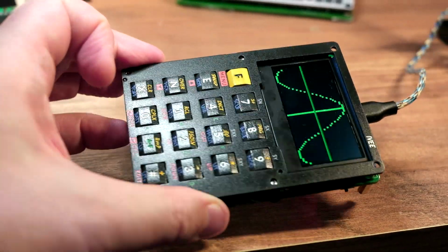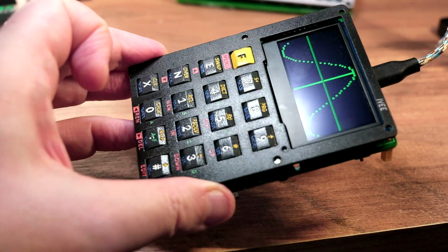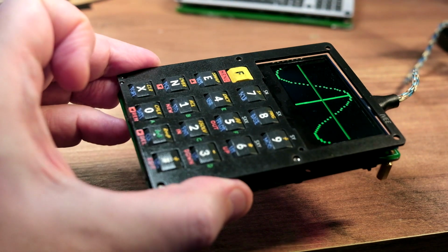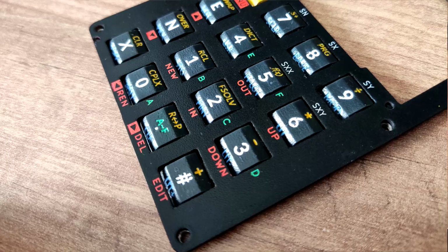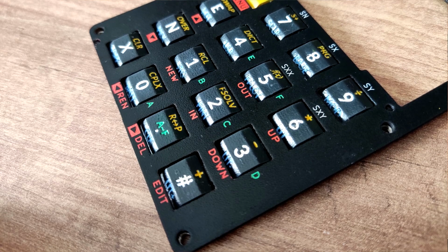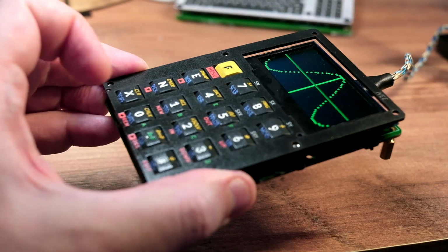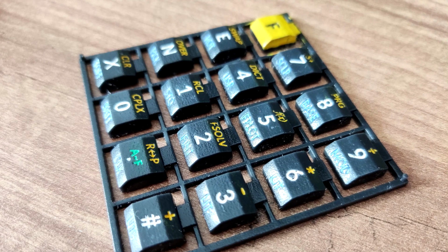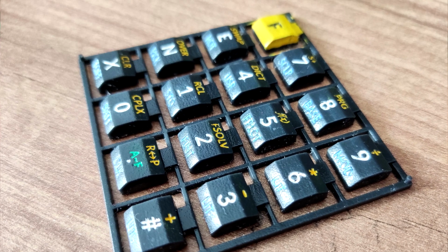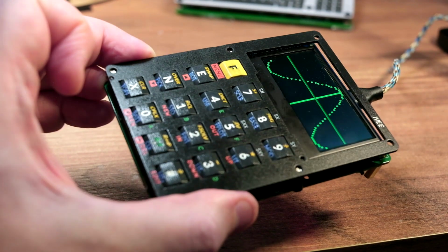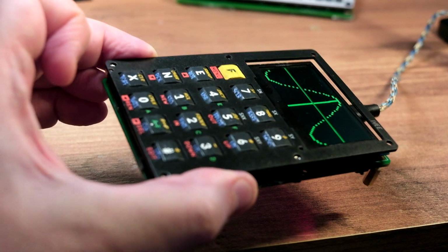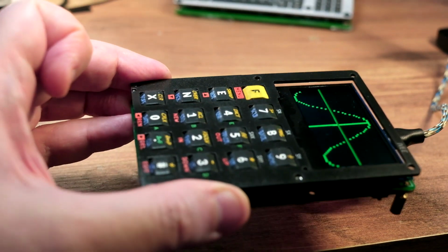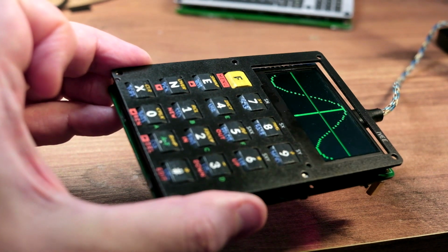It's pretty hard to see, but it should be visible at some light angles. And they're printed like that by 3D printing services. This is a high resolution print in resin. And then I just filled in the engravings with various paints, water-based paints, because they're very easy to correct when you make mistakes, and it's impossible not to make mistakes while doing this. And then everything is fixed with a transparent varnish, acrylic-based varnish.